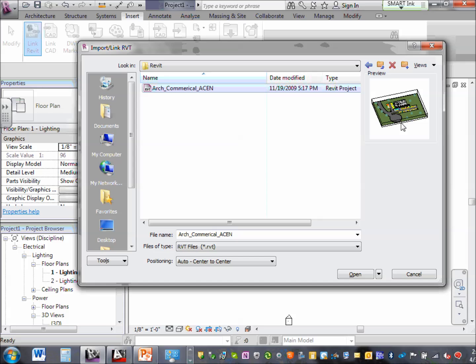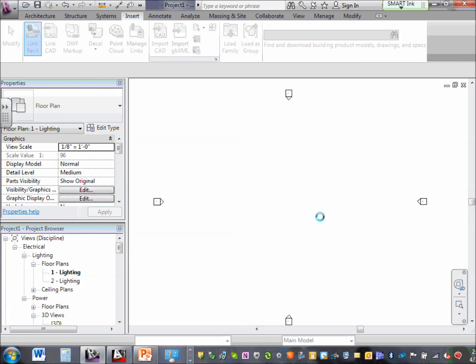Okay. So when you're loading and synchronizing, you're going to say something like loading and synchronizing with central. Every time you hit synchronize, when you're done with your work, you take all your work and shift it to the central file. We're not doing a central file yet, but we're going to import that one, link to it. Okay, so when you guys go there, here's what you clicked on. Then you're going to go Auto Central. They have multiple options of doing it. I keep Auto Central here and open.